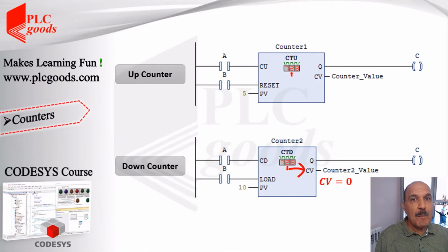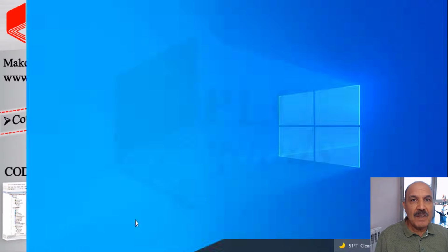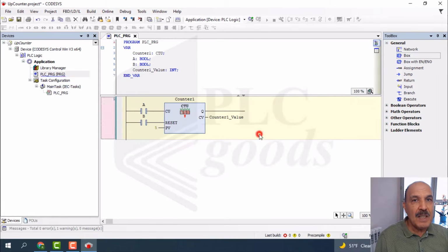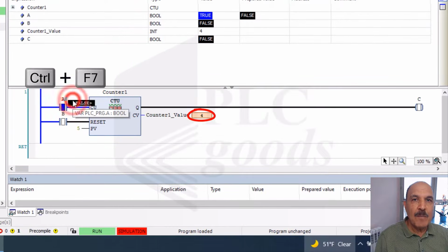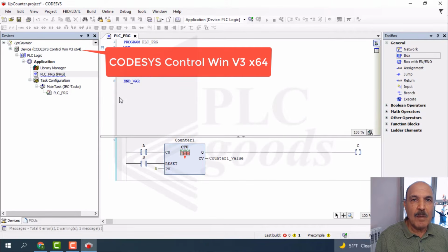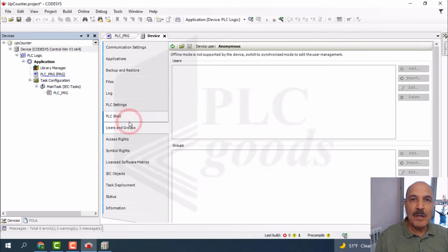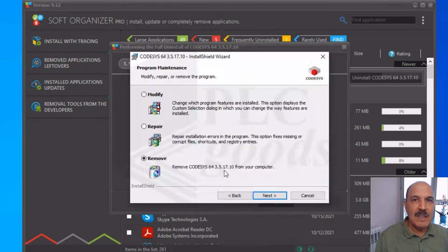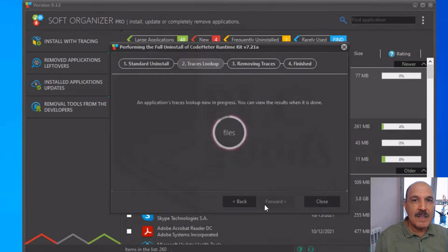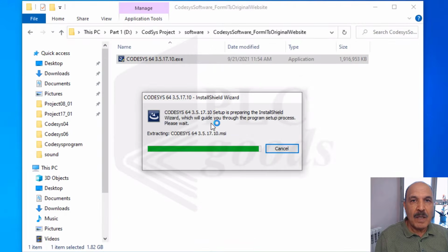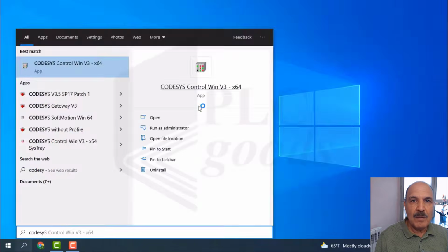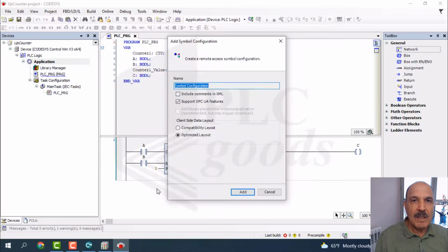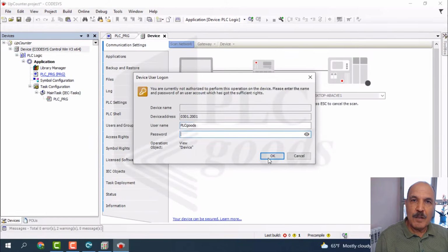In video lesson number 6, the focus shifts to counter instructions in PLC programming, especially the up counter or CTU. This fundamental component counts upwards with each rising pulse on its input, activating an output when the counter limit is reached. The tutorial highlights the necessity of variables for counters and provides an overview of down counters and up-down counters, which count down and both up and down respectively.